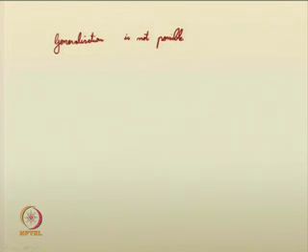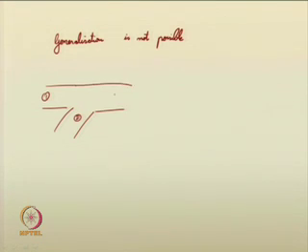If we want to analyze it in a brief way, for example, in Ven Te Chow's book it is mentioned that if channel 1 is coming like this, channel 2 is merging, forming channel 3, such a situation is combining flow. This is a case of combining flow from different channels.